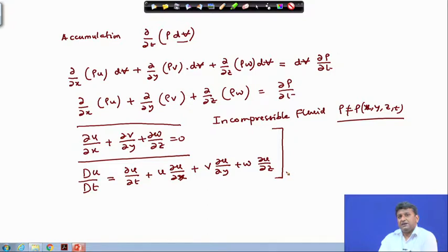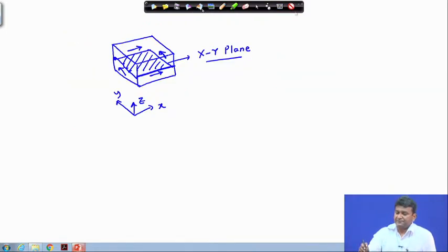ways. First, I will show you how it can be very easily handled by simply considering the nature of fluid acceleration, that is the concept of substantial derivative in Newton's second law straight away. However, for the benefit of the students, it is strongly encouraged that you again draw a control volume and show at each phase due to each of the velocities the momentum is actually getting transferred into the control volume. That will really help each one of them to have a very good concept on this particular matter.